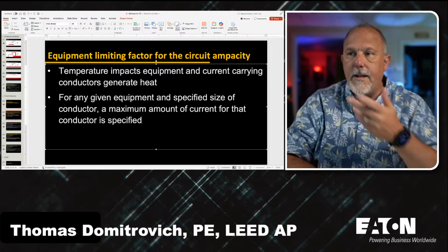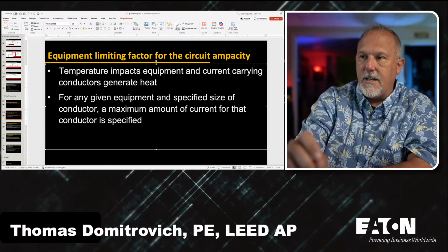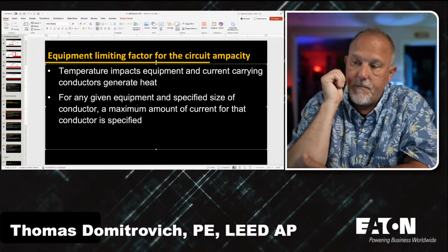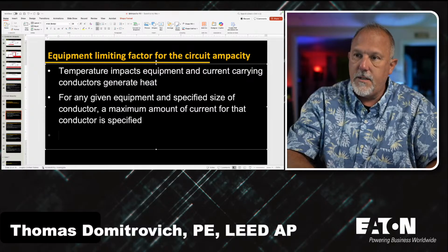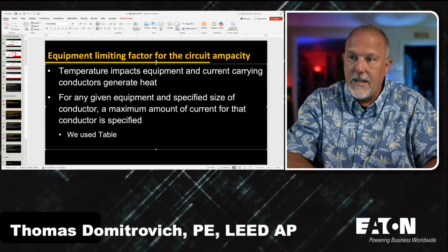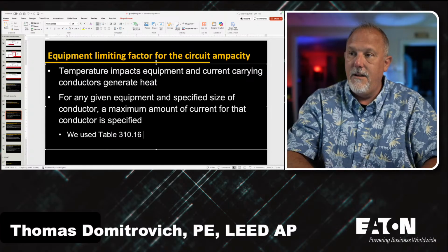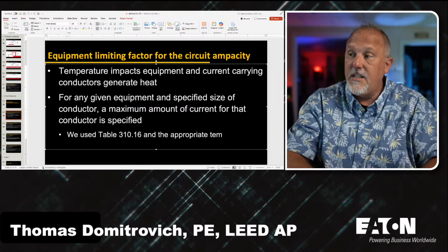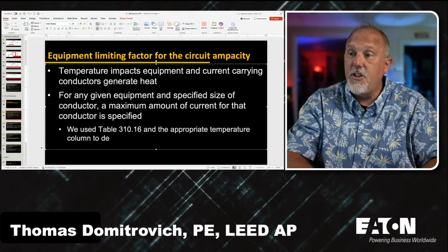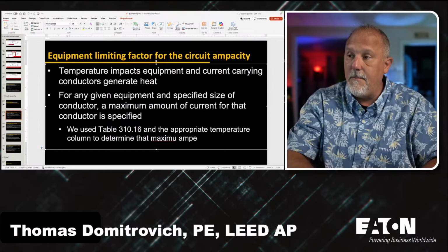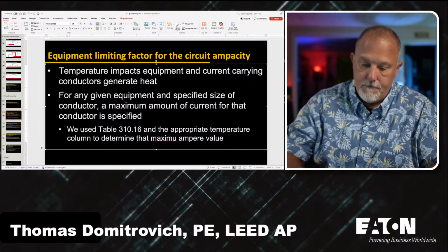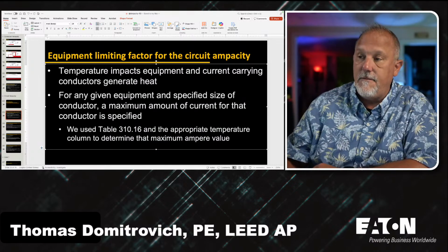for the equipment, right? So the specified size of a conductor, a maximum amount of current, and we use Table 310.16 and the appropriate temperature column to determine that maximum ampere value. Right? Makes sense? We know that for a fact.